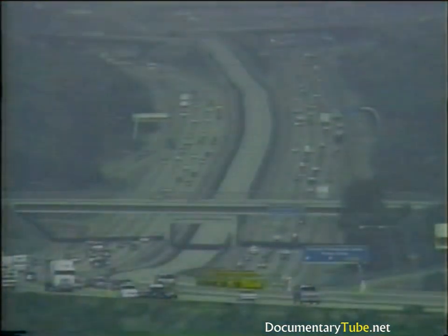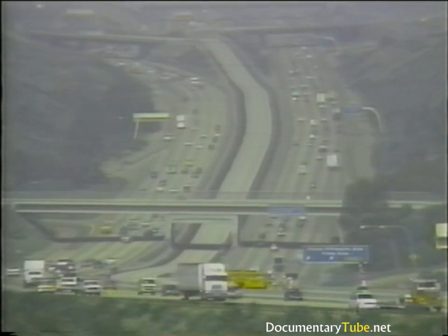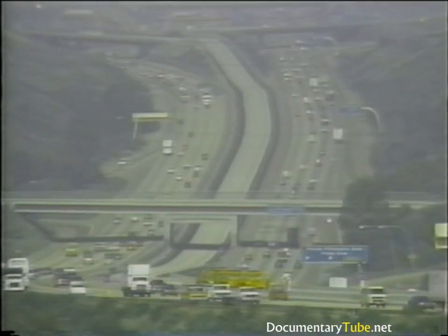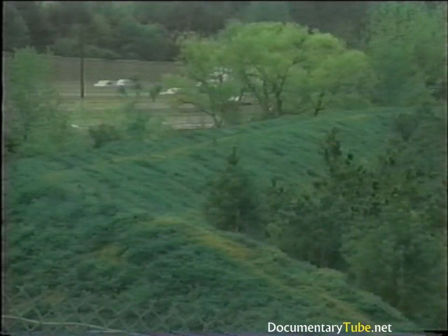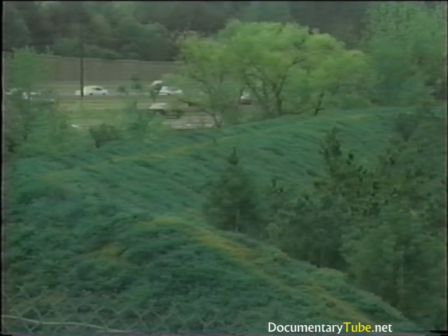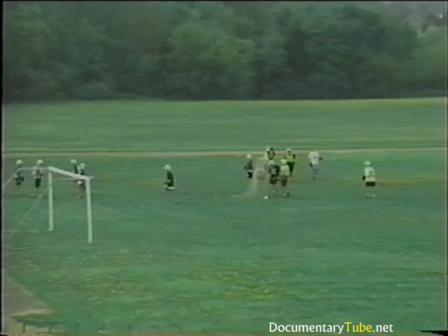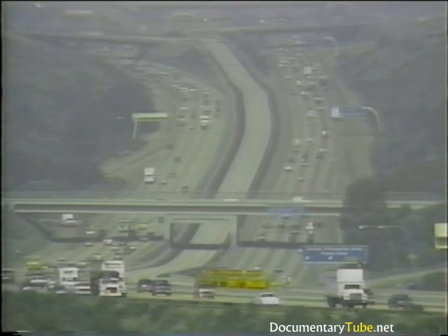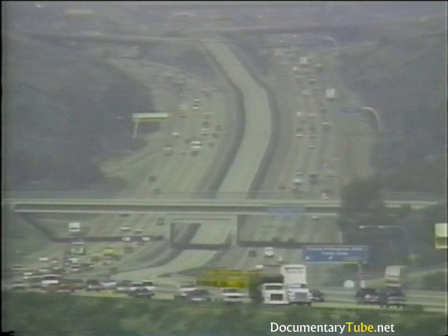We have so far discussed several aspects of the sound propagation path, and have now arrived at the last topic covered in this presentation: obstructions in the propagation path. Natural terrain features, such as hills and dense woods, as well as man-made features, such as buildings and walls, obstruct the sound path between source and receiver, and in most cases reduce or attenuate noise levels for nearby receivers. The amount of attenuation provided by these objects depends on the size of the object and frequency content of the associated noise source.